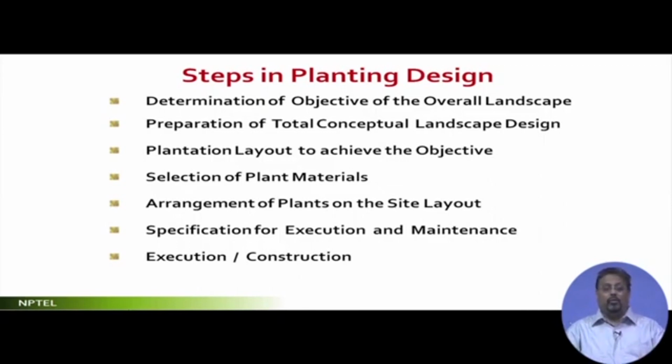Yes. I'll suggest that if you are practicing landscape architecture, then please insist on reviewing it periodically. That means supervise it periodically, and don't leave any ambiguity in your specification or BOQs. You remember I discussed BOQs, bills of quantities, in the schedules in the initial classes. Don't allow the contractor any opportunity to do whatever he wishes within the legal ambit. Now, if I am focusing on planting design, you specify the species, its location, its placement, the distance between a pair of plants, and what maintenance has to be taken care of, meaning how it is to be grown.